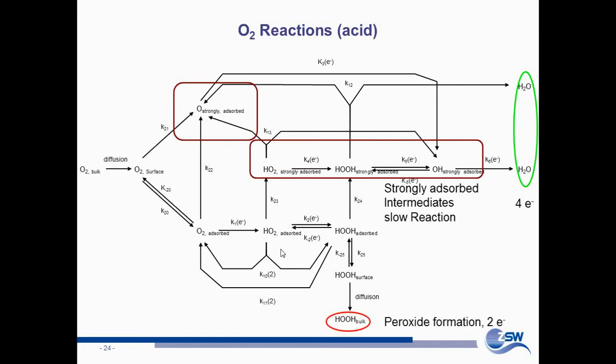And we have a side path to oxygen reduction, which is what we call the 2-electron reduction, where we don't go into water as a product, but we end up with hydrogen peroxide as a product. So we have less current efficiency in that respect. We need more oxygen to be reduced at that point. And the second issue is hydrogen peroxide in the presence of organic materials is somehow aggressive, and well, we face trouble with hydrogen peroxide when running any kind of electrolyte membrane.